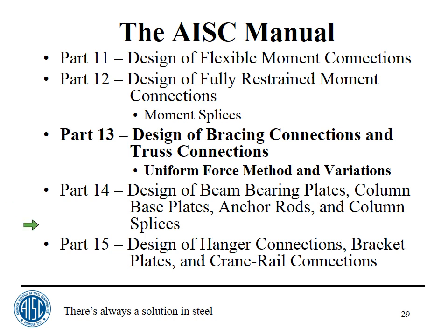These are connections that are supposed to be able to take wind, and I really haven't done anything with them recently, but there's a bunch of papers that Bob Disque wrote some years ago that showed how to do this. Part 12 is basically moment connections, fully restrained moment connections, and also moment splices.